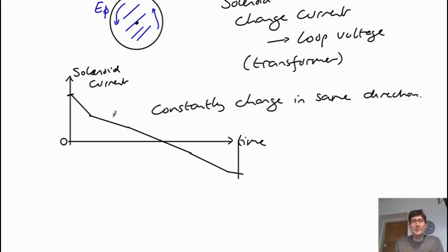Okay, so there are some limits to this. So clearly there's a maximum current that we can put in the solenoid, and similarly there's some maximum negative current. So there are some limits to the range that we can drive, the maximum currents we can put in the coils. There's also a heating problem: when you have currents in the coils, they tend to warm up, and the longer you have the currents on, the hotter the coils get.